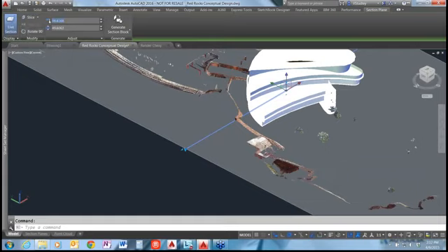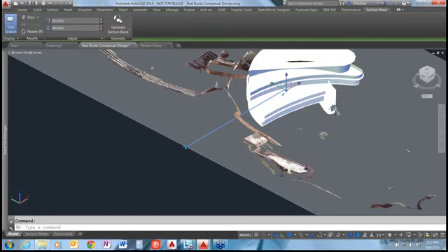Here you'll see the section offset. This is offsetting from the start point of your section. Let's say I put in 20 as a starting point, and you should see that section jump a little bit. And this right here is the slice thickness, and it is controlling the thickness of that slice through your model.